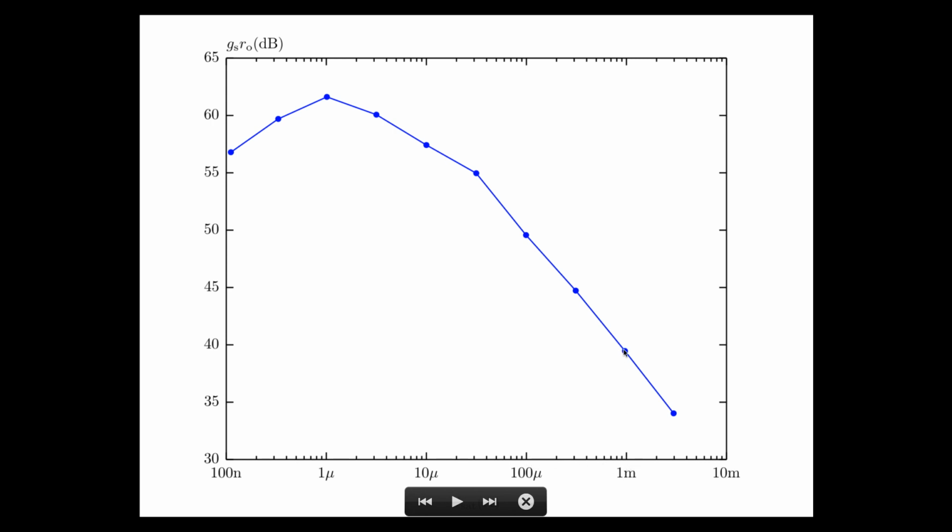And we can see here pretty clearly that these 2 points are almost precisely 2 grid spacings apart, which is a change in gain by 10 dBs, which is half a decade for a 1 decade change in current. So that's exactly an inverse square root relationship.